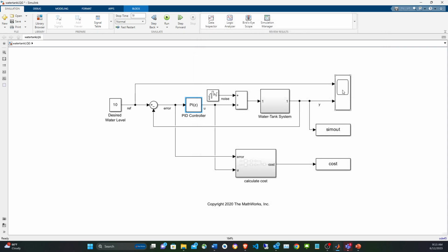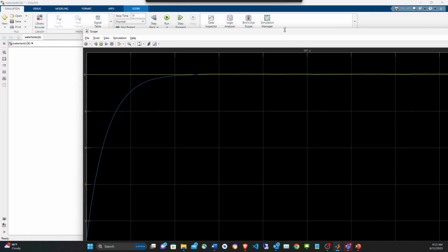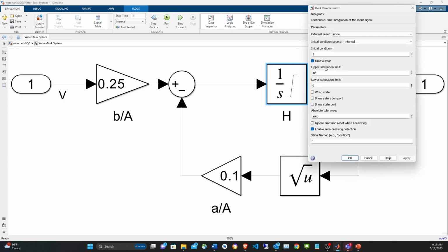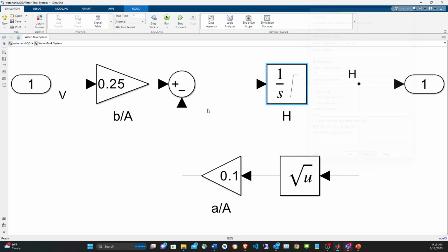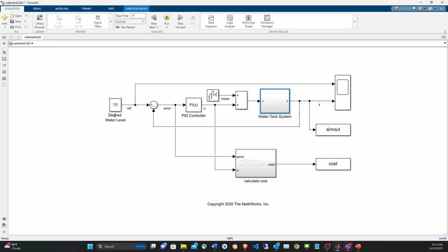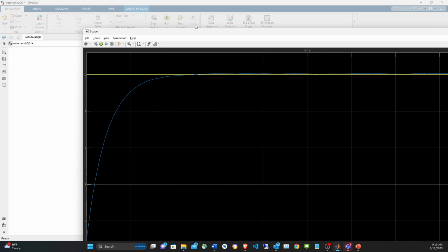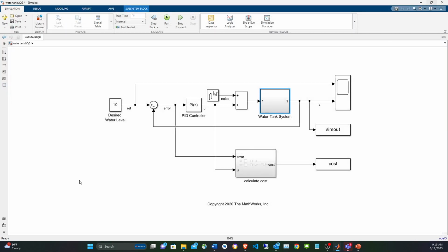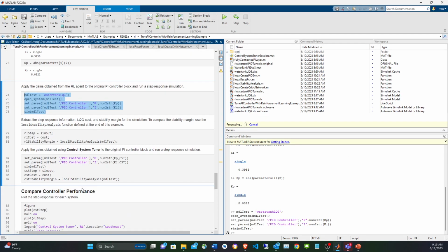Okay, so now let's take a look at filling it, but first make sure that the initial value of the tank is low, is 1. So we're going to go from 1 to 10. Let's see, Control T to simulate, and you can see that it performed well. It went to the level 10. It jumped a little bit, but eventually got close to 10. So the control behaved fine. And now let's compare it to the classical optimization.